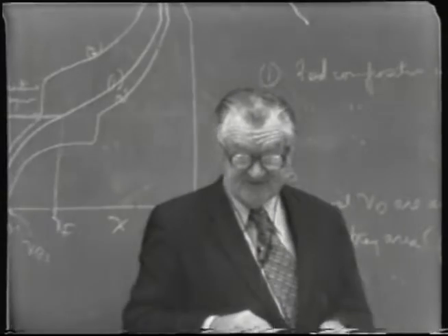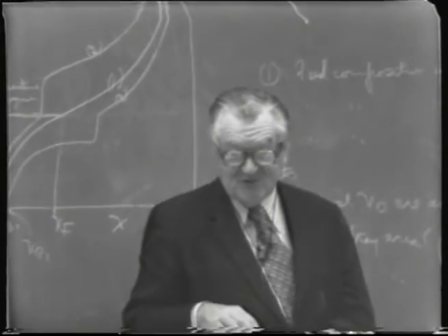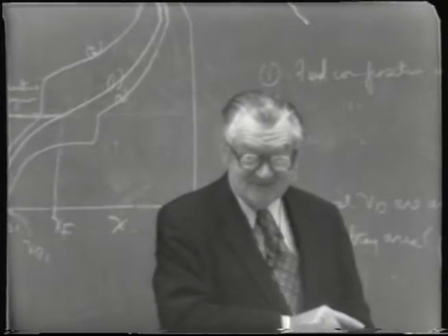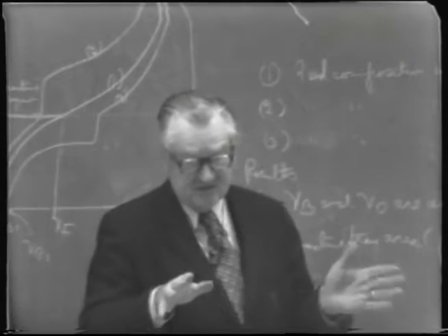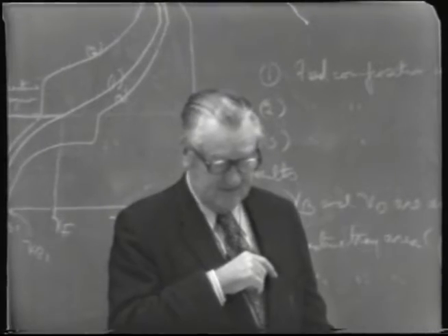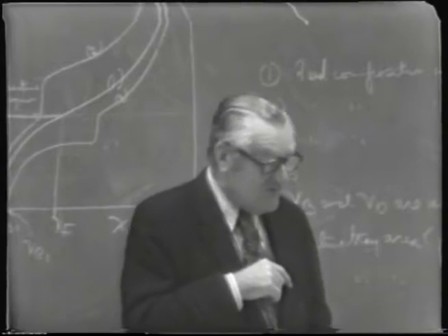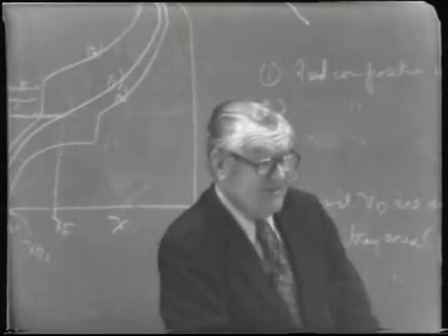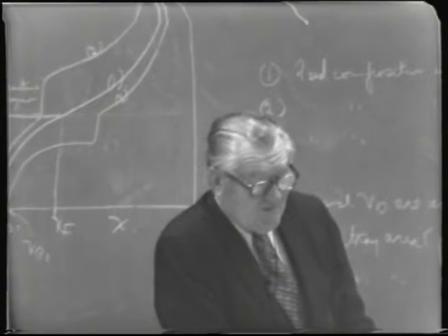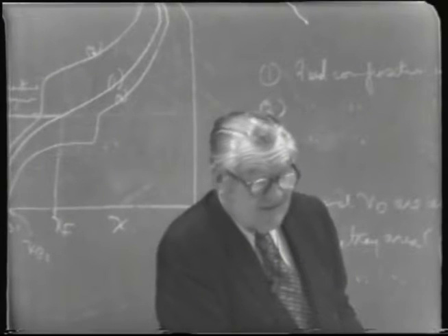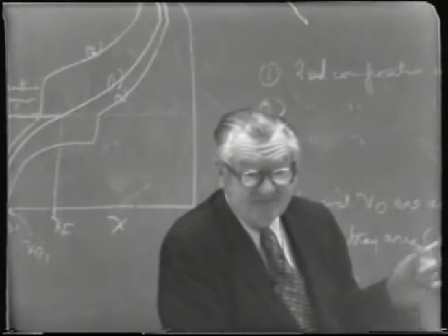It should be obvious now that if you're trying to approach zero alcohol as a limit, it'll take an infinite number of steps, because the very nature of distilling columns is that you cannot get every molecule of alcohol out of the liquid, out of the feed. You approach zero concentration of the volatile component as a limit with an infinite number of steps.